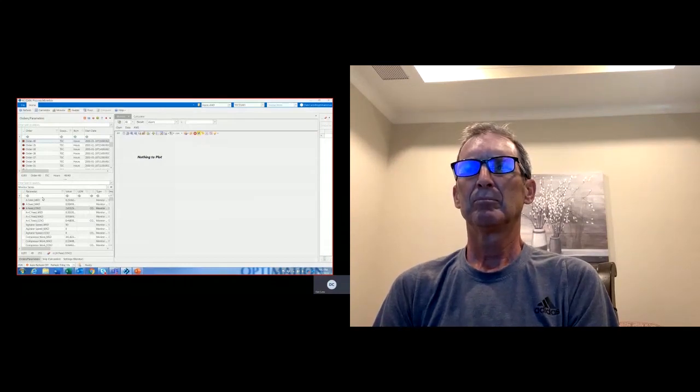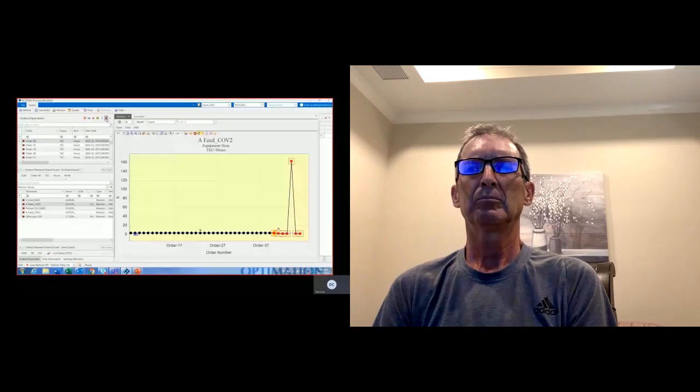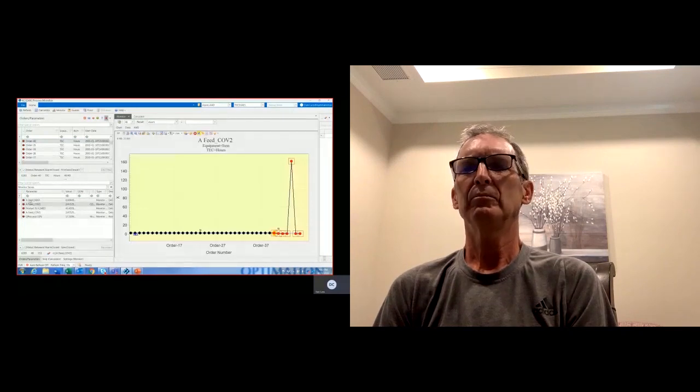And you can see this little bell on the side shows that there is an alarm for that batch. And coordinating with those bells, you come down to the parameters. The individual parameters that are in alarm also have a bell. Feature here, if you click this button, it will remove the parameters for the batch that are not in alarm, the things that are not within the control limits that are defined, and then the ones that are in alarm show up here.